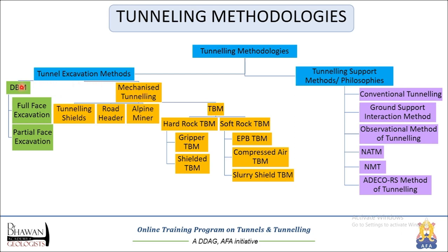In drill and blast, which is shown in green color, we may have full face if the rock is good, or if the rock is not good or the tunnel is being constructed through soft sediments or riverborne material or any kind of overburden, we will have to resort to partial face excavation, which is also known as multiple drifting method.